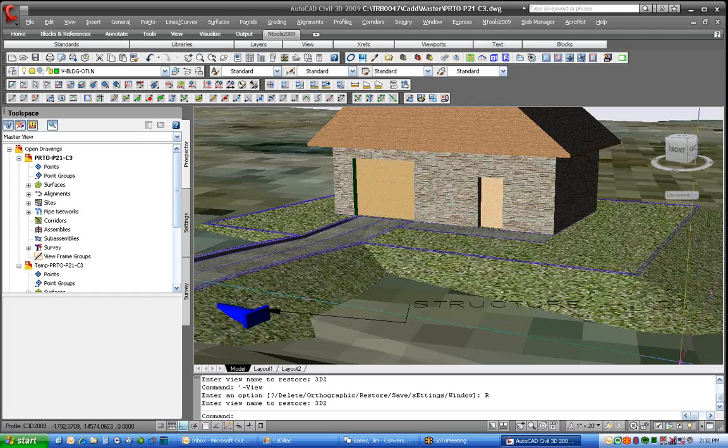So what I did is applied a grass material to the entire surface, drew a polyline where the driveway and patio or the sidewalks were, said those are concrete or asphalt or whatever. We threw a pipe in and didn't apply any materials to that, so it's just rendering as blue. And then just real quickly assign to these two solids. You can assign materials to the faces, and we got those right out of the tool palettes here.